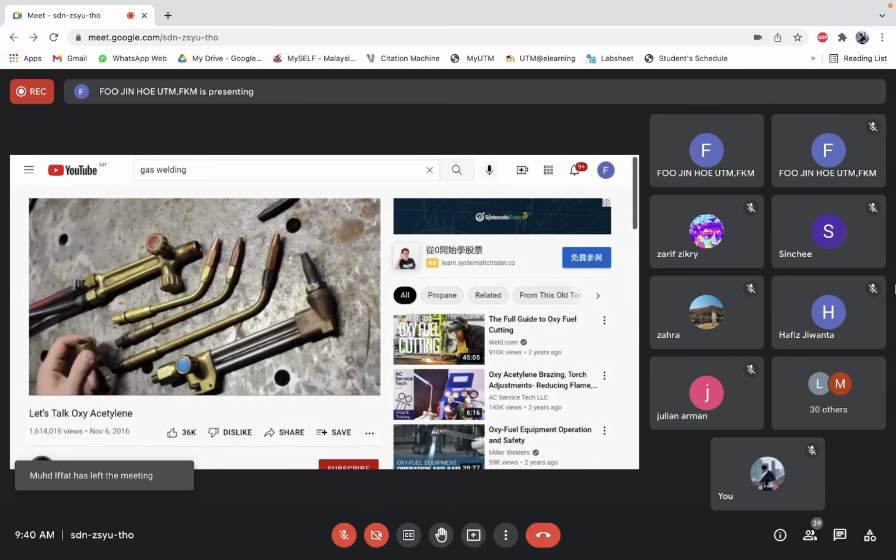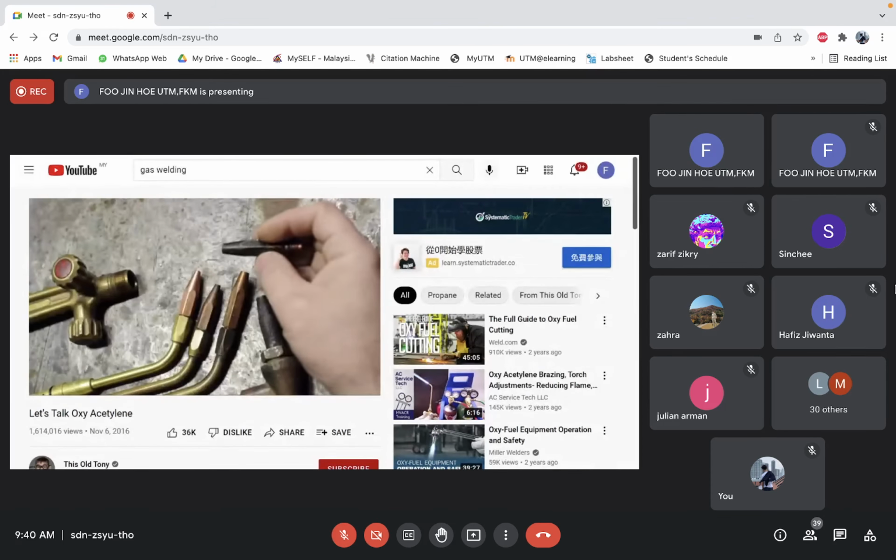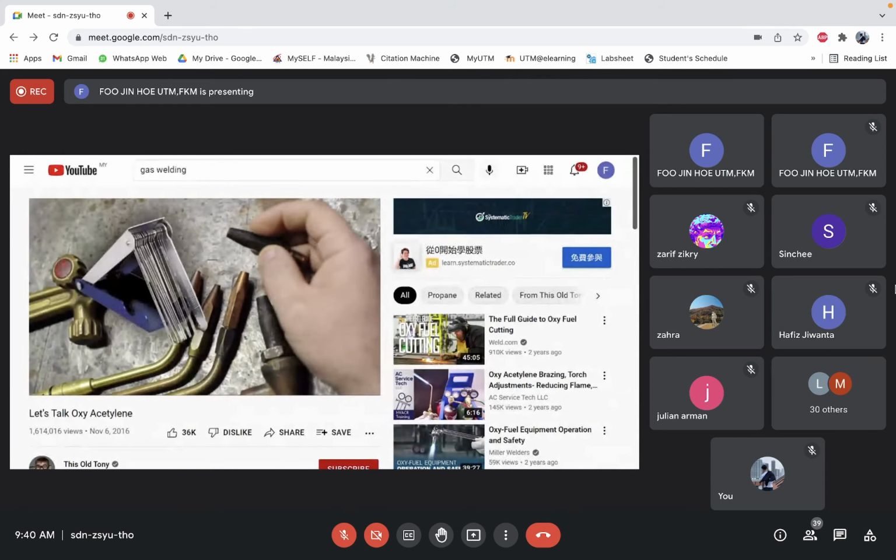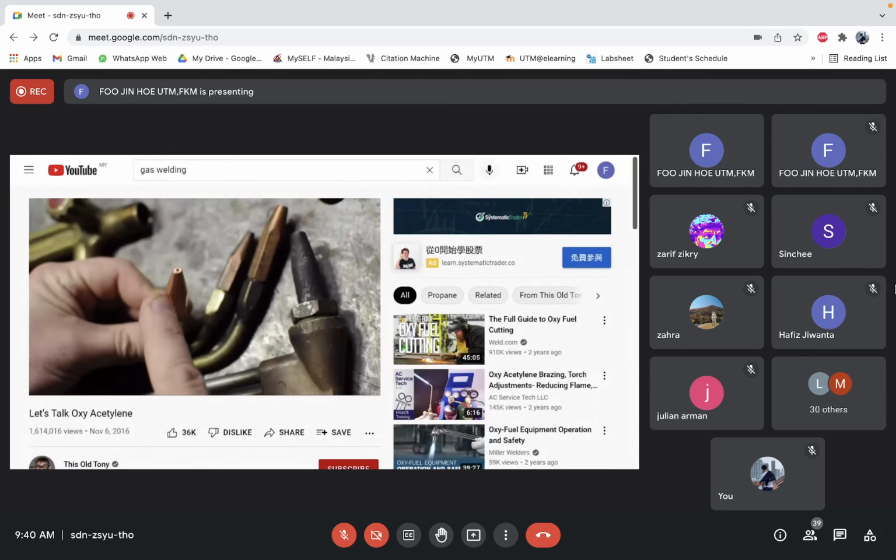All right, well, we're not quite down to brass tacks, but we are almost cooking with gas. I picked up some new tips for my torch. Tips can be cleaned with a special tip cleaner, but sooner or later they wear out and you need new ones. Tips are sized by orifice diameter, either the size of the hole or some made-up number, like a number 2 or a number 4.